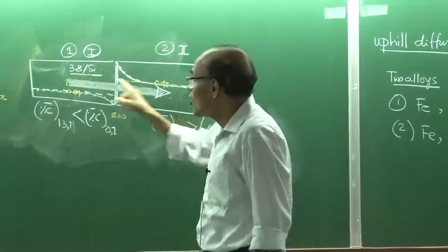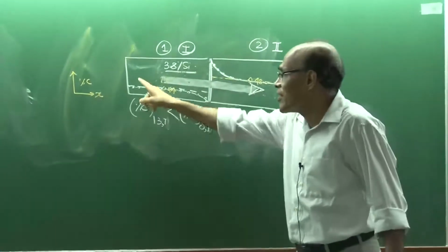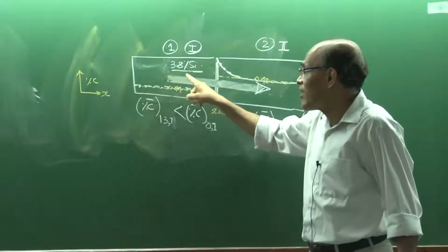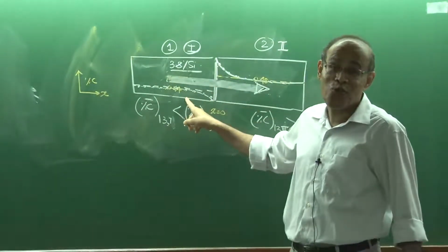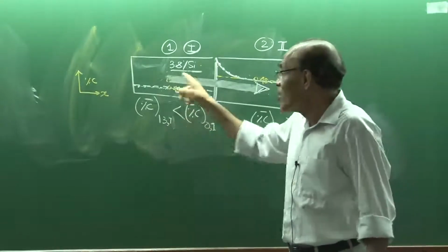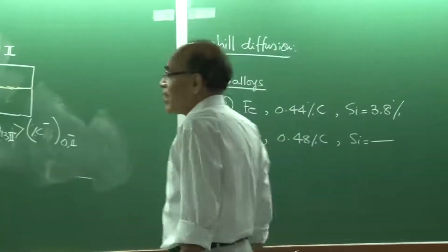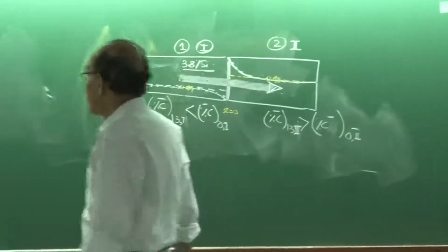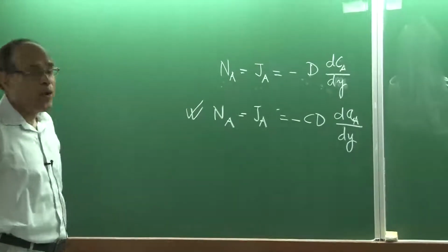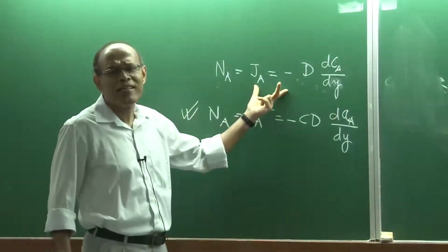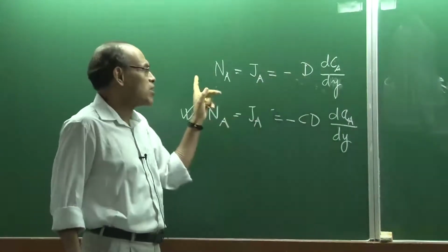Similarly, here also, if after a very, very long time you measure the activity, you will find the activity here, here, here, across it is going to be the same, but the concentration profiles are not going to be the same. Because we are talking about a multi-component system, and that is basically the uphill diffusion process. Therefore, to analyze a scenario with a single component or two-component system where the activity reduction or enhancement is not so significant, this expression would suffice.